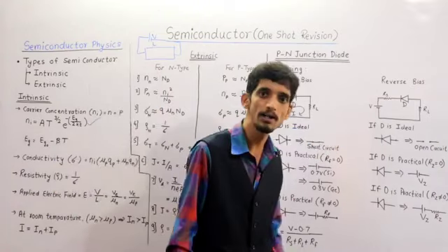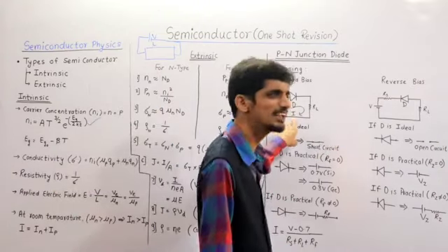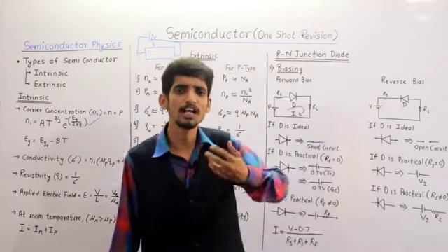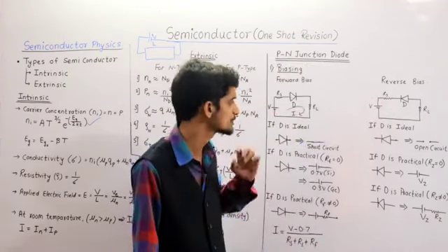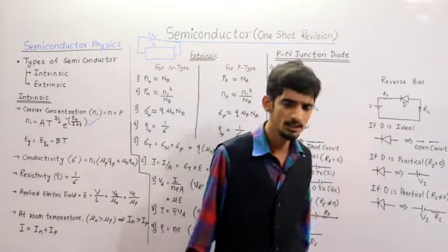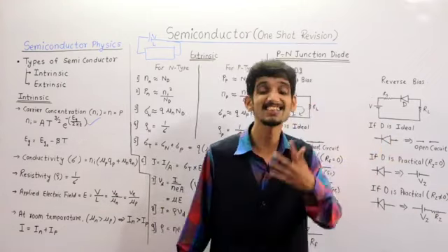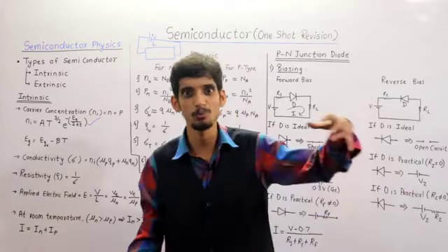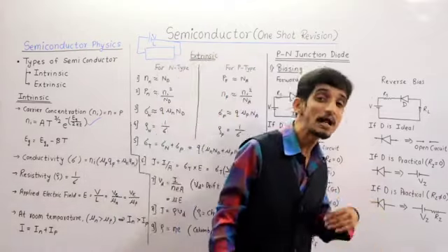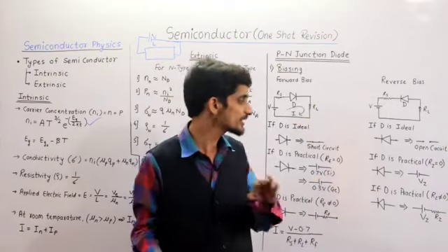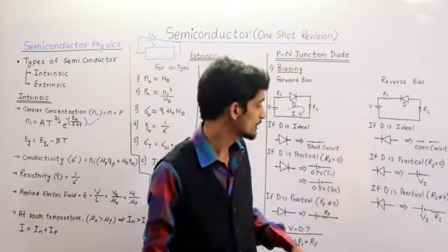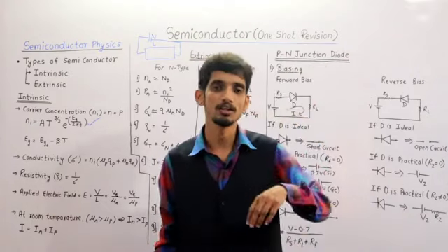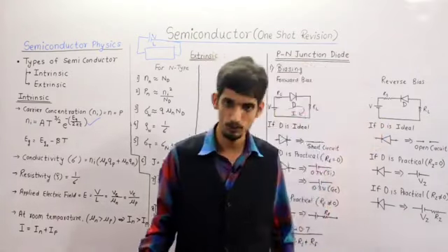If you consider reverse biasing of the diode, the same circuit can be connected, but the positive terminal is now connected to the cathode, meaning the cathode is more positive than the anode, that is a reverse bias. If the diode is an ideal one, then in reverse bias it acts as an open circuit. That's why the current in reverse bias is 0, because the diode is open. Now if the diode is practical, it means what? It does not act like an open circuit, but it acts like a battery of the applied reverse voltage, or breakdown voltage.